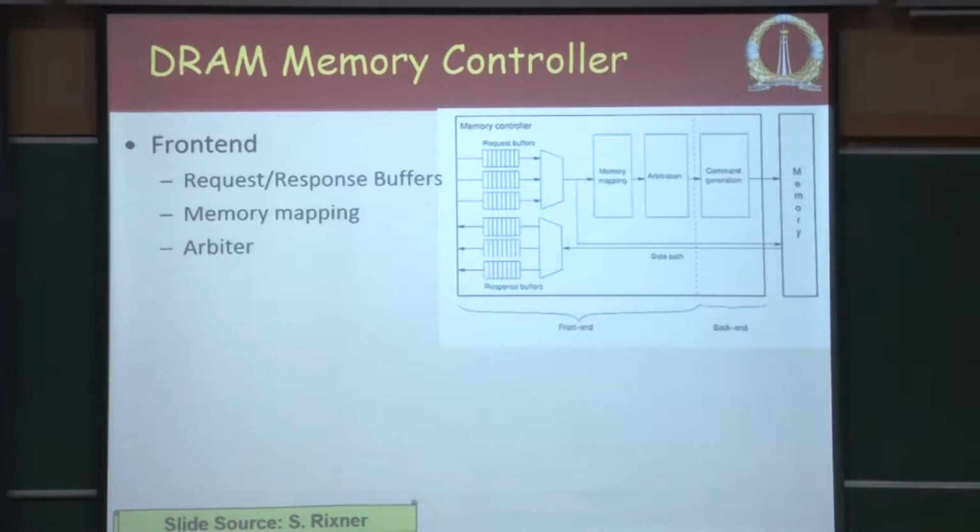What are memory bursts? The read bursts and write bursts. I mentioned these transfers to you, correct? Once the data is fetched, it has to be transferred back to the memory controller. It is going to take multiple cycles. So this is basically the burst that they were referring to. This incurs additional energy. It is related to the number of cycles.